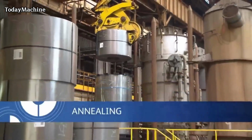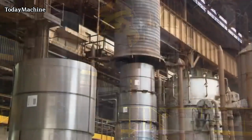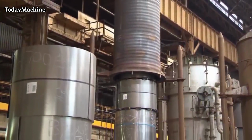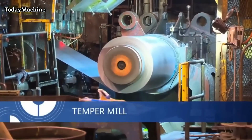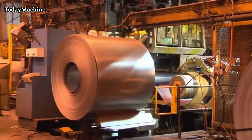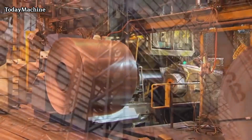After the cold rolling process, the coils may undergo annealing to relieve internal stresses and improve the steel's mechanical properties. Annealing involves heating the coils to a specific temperature and then slowly cooling them. This process enhances the steel's ductility, toughness, and formability.